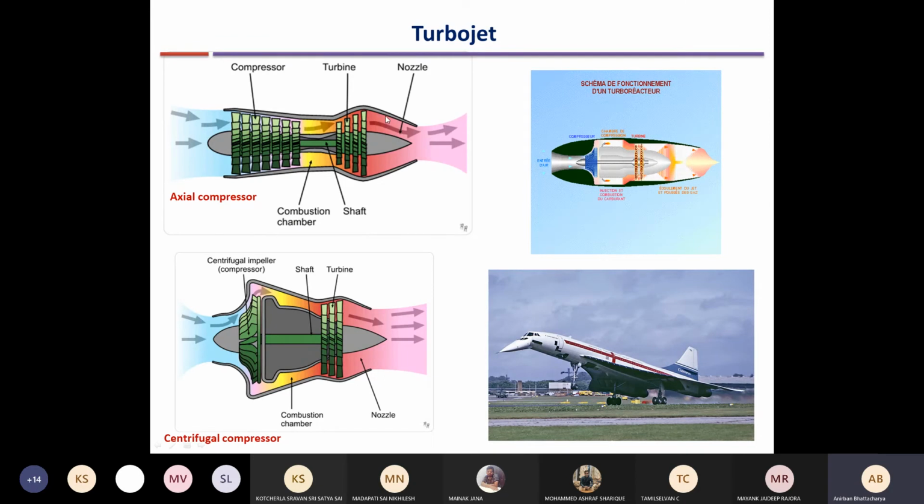Okay, so you get high velocity at the inlet. Unlike industrial gas turbines, the jet engine is flying itself. It is flying at very high velocity, around the speed of sound. So around say 900 km/h or 1000 km/h speed, or even larger. Nowadays, military aircraft use turbojets. So turbojets operate at Mach 2, Mach 1.5, around those speeds. Okay. Supersonic speeds. At subsonic speeds, nowadays we don't use turbojets because the propulsive efficiency is less for a turbojet.